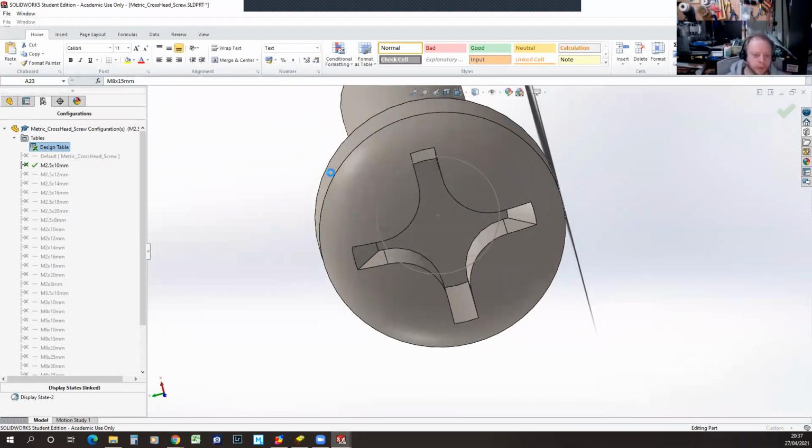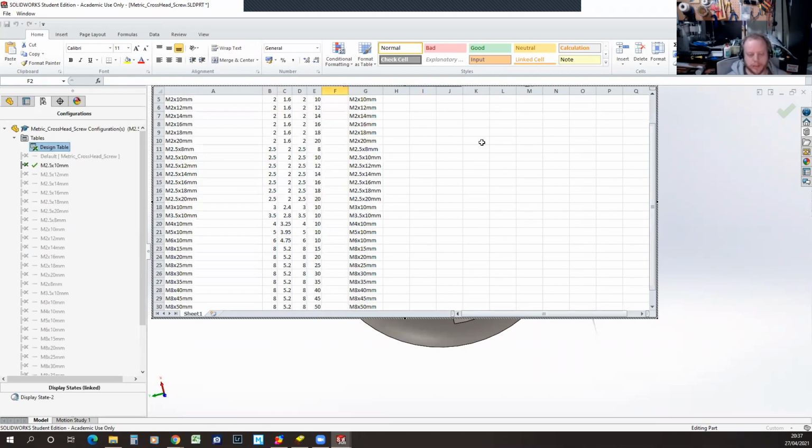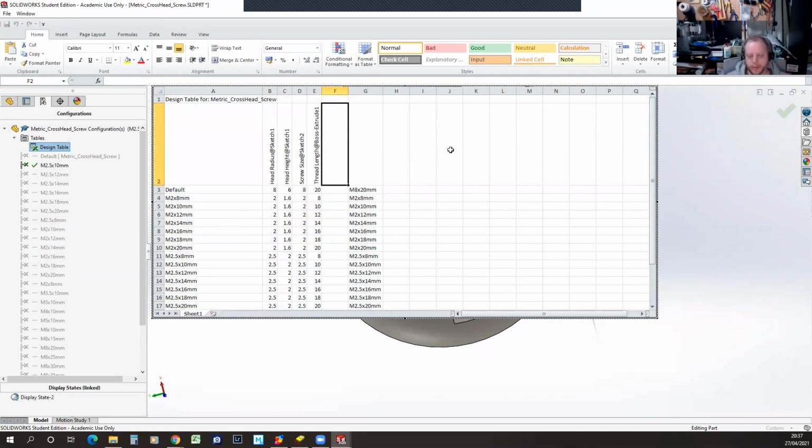One thing I've actually found helpful is that data sheets for parts sometimes do have equations you can just put straight into a CAD app. As in, when you're looking at a data sheet and you see there's only half the dimensions you're looking for, you might find there are equations for the others. Oh, that's useful to know. I've not spotted that before.